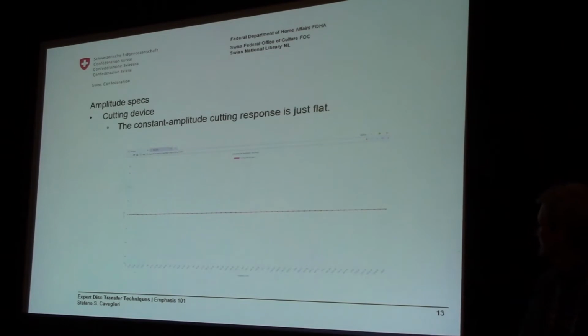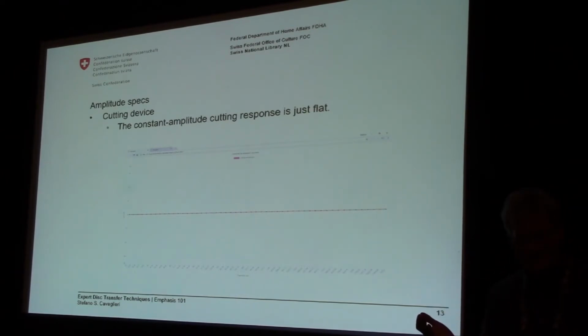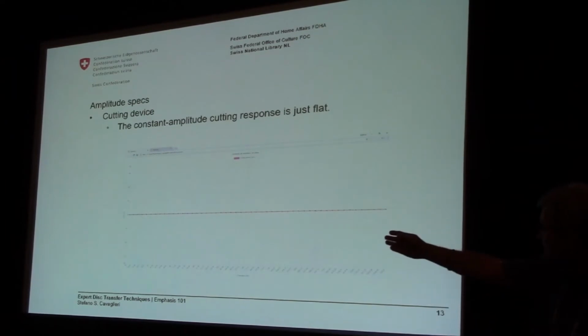So I hope you can see the red line in the middle. If we look at amplitude specs, for a constant amplitude cutting device, the response is just flat, from 20 hertz to 20 kilohertz, ideally.